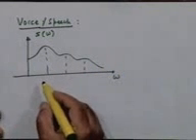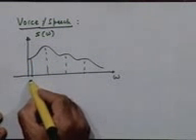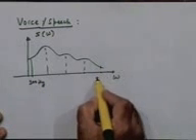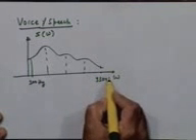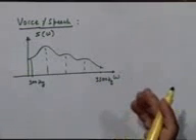And for telephonic communication, it is found that if you concentrate on the energy between 300 hertz to about 3300 hertz, right, you capture most of the intelligence as well as essence of speech, without losing much on either the intelligence or, let's say, the quality of speech, right.